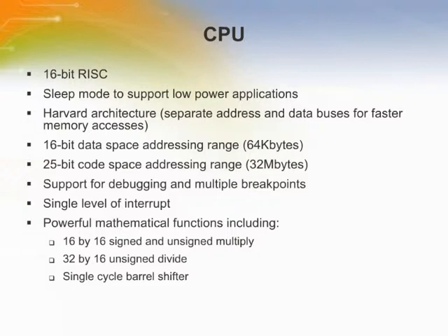The eCOG1X has an advanced high-speed, low-power CPU with a powerful instruction set targeted at high-level languages, in particular C. The CPU is capable of operating at speeds up to 70 MHz. The CPU has a Harvard architecture, which means that it has separate buses for code and data spaces. The eCOG1 instruction set includes 42 instructions with 6 addressing modes. Most instructions operate on 16-bit word data values.